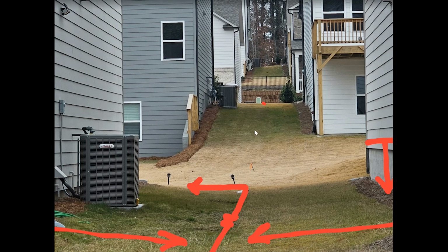Zooming in on a rear view of the basement lots, we've got that high point there, and then we have a wing wall coming off just to keep that dirt away from the rear of the house so that we could have a nice flat backyard there. Again, just showing, hey, this is the yard going out there, that we try to keep like 15 feet away from the house at a 3 to 5% drop going from the rear of the house out to the back.